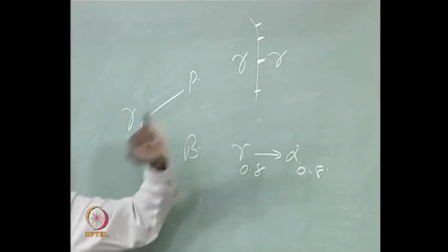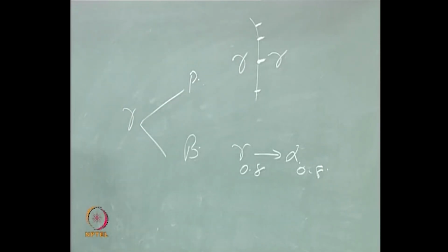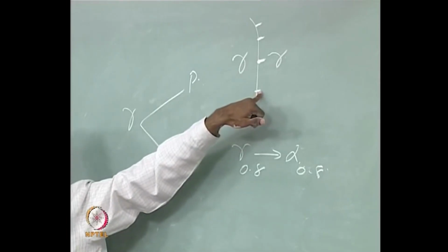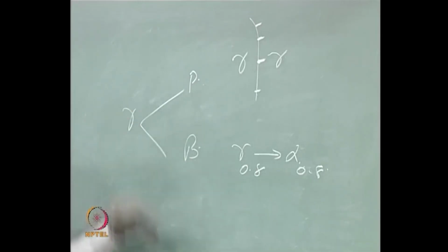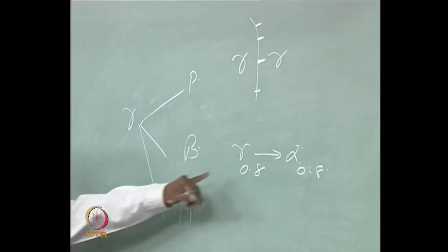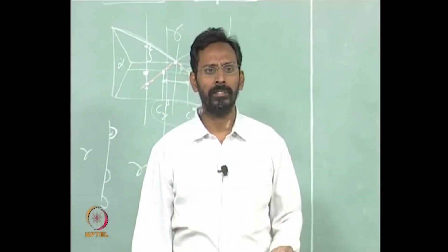you can easily form a nucleus. That is the reason why, and carbon can happily move at temperatures closer to 723. So that is the reason why cementite is a nucleus there, whereas here cementite is not able to be a nucleus, carbon is not able to move. And if you go further down you get martensite, because even that small short range diffusion is not able to happen, and finally you get a diffusionless transformation. Tomorrow we will talk about this. Okay. Anything else?